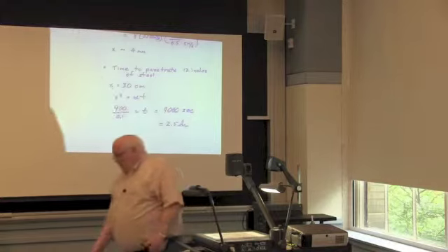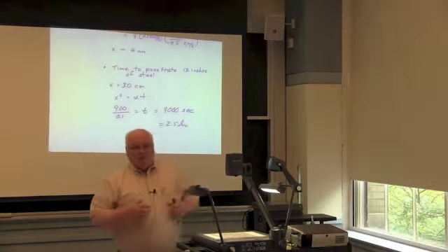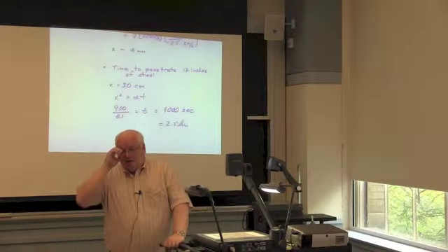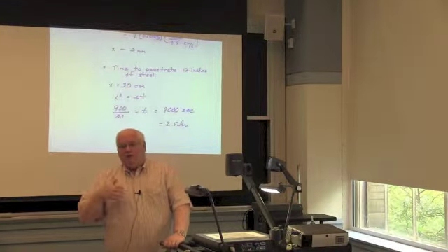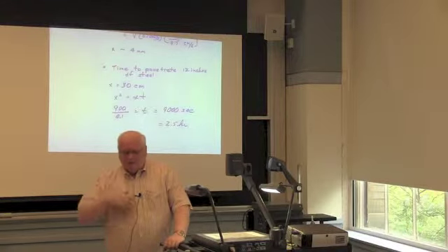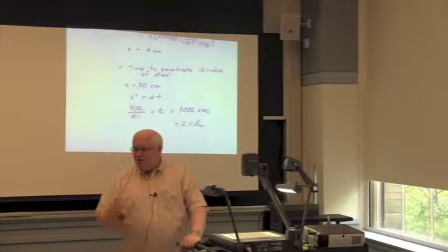Well, actually, it didn't crack right away the second time. The first time it cracked right away, as it was cooling down, they heard a bang, and a crack propagated. The next time, they gouged out and didn't make a partial penetration weld. They decided they needed a full penetration weld, which is what you actually see. And this one actually survived. They said, it's holding together, no cracks.